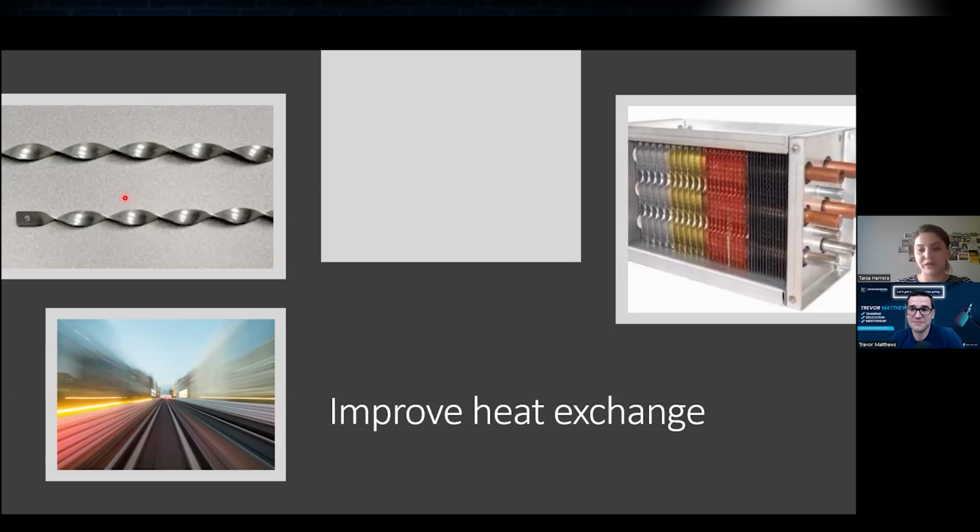I want to add something about counterflow and parallel flow. Parallel flow is suitable also for ammonia flooded evaporators. Any direction of the air can be used, even counterflow and even parallel flow. You get almost the same capacity. Excellent. Yes, it depends on the application and, as mentioned, the refrigerant. The properties of the refrigerant have a significant impact on this type of thing, and the circuiting and everything. Thank you very much.